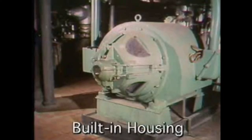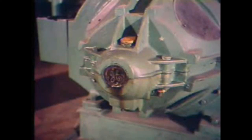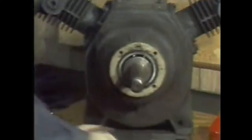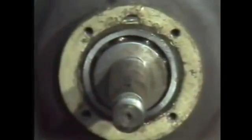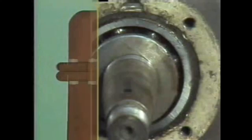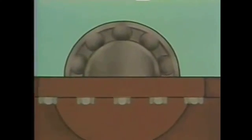A built-in housing is actually part of the machine casing. In many cases, the shaft and the bearing are completely contained within the machine. To reach them, the casing must be taken apart. Built-in housings may also be solid or split. The solid types of built-in housings usually have removable end caps. Removing the end caps allows the bearing and the shaft to be taken out of the machine so that the bearing can be worked on. With a split-type built-in housing, there is a joint in the machine's casing that must be taken apart to get to the bearing. This allows the shaft and the bearing to be lifted out so that the bearing can be worked on.